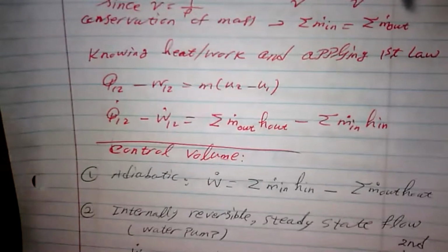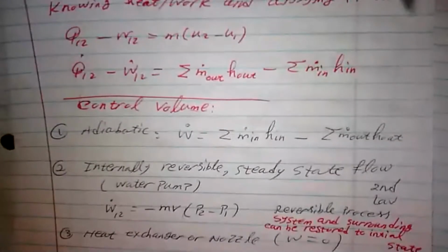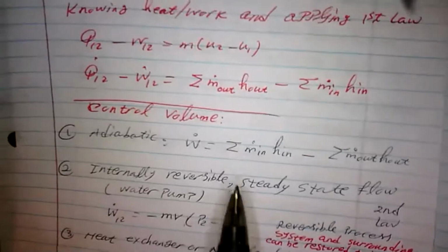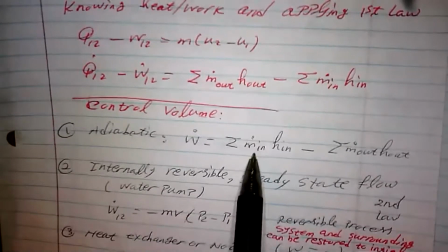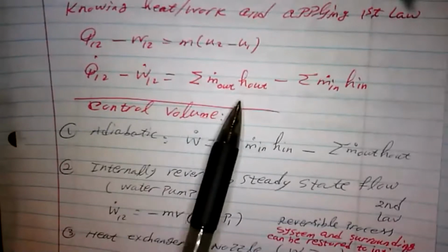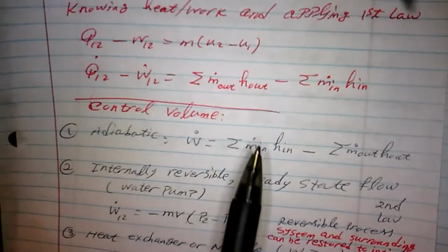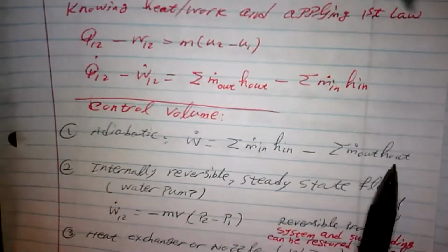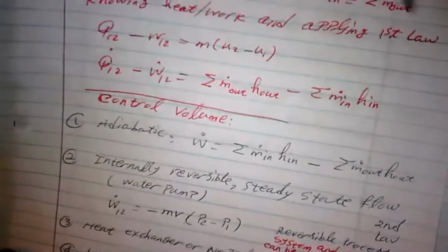And then if you have an adiabatic system, we have Q is 0, so W dot, you'll rearrange this here, okay? So we're going to have it for the control volume. So we have m dot in, because there's a minus in here, so we distribute the negative to the right side also. Times -1, so we have a positive W dot equals minus m dot out h out plus m dot in h in. So that's a simplification.